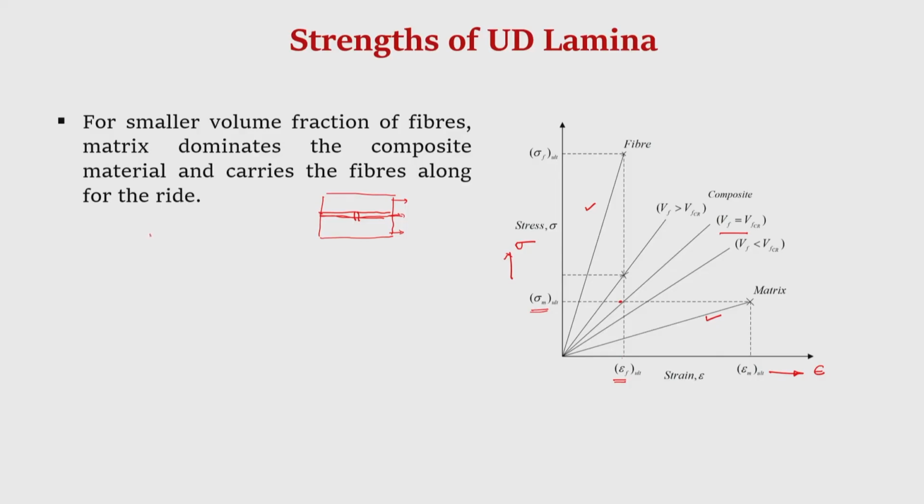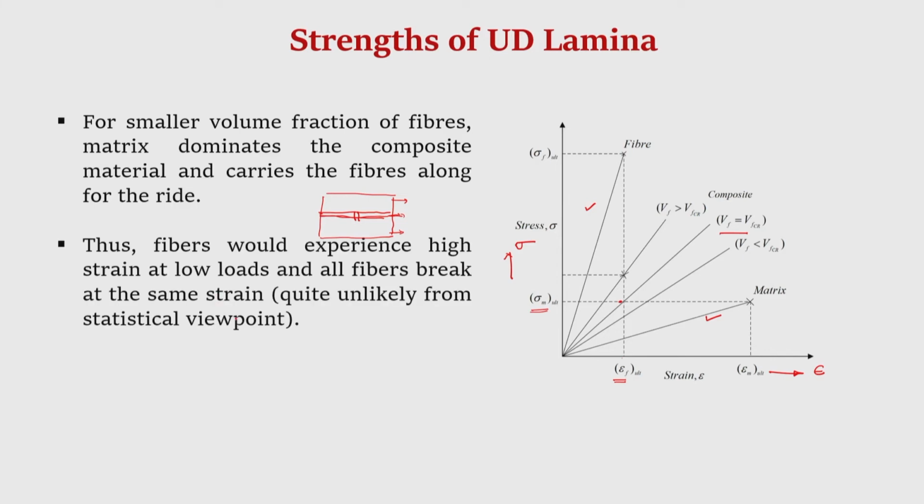Okay. Now, what is the stress in the composite? The stress in the composite, sigma c, is equal to sigma f V f plus sigma m V m. Now, when the fiber fails, suppose there is one fiber, as in this example, when this fiber breaks, it cannot take part in the loading, only the matrix will be carrying the load. Therefore, sigma f is equal to 0.